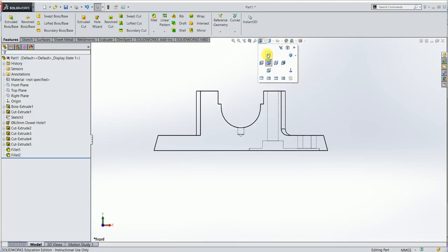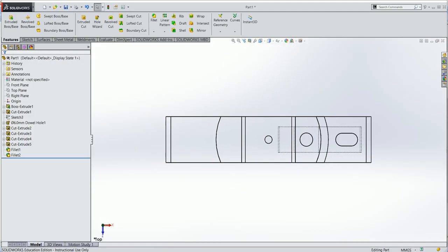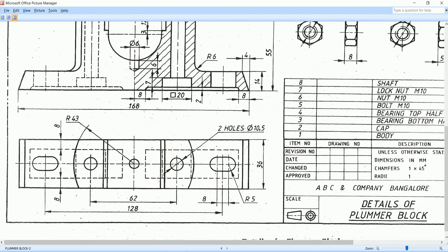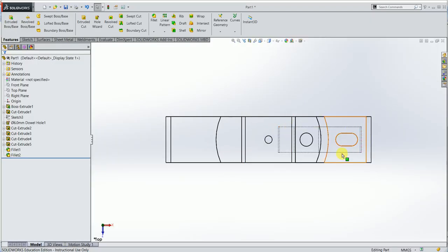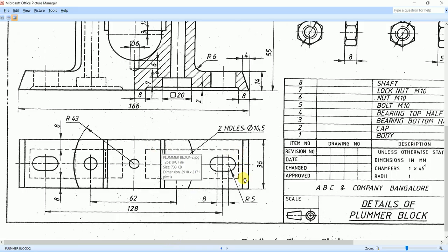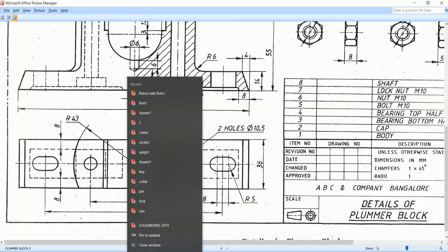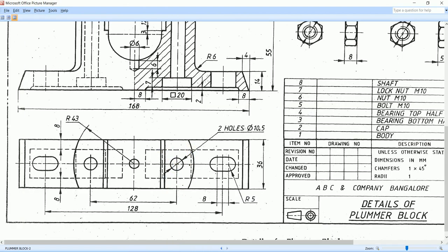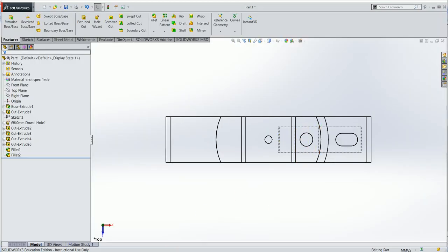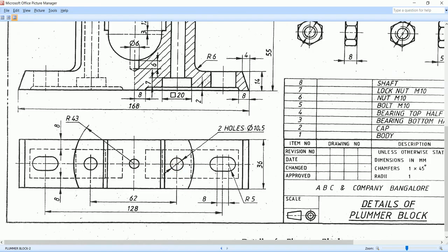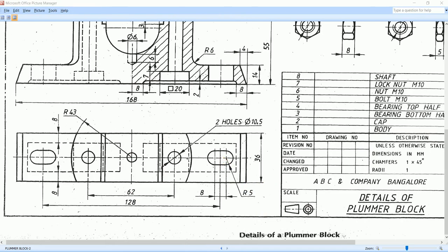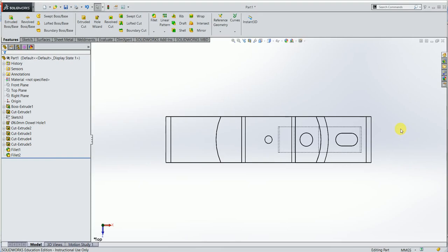And let's try to compare the top views. So now this is the top view. You can see this dashed rectangle here corresponds to this rectangle here, and somewhere here we need to have a square rectangle with dashed lines. That can also be seen here. And we have the circular wall here, which can be seen here, and we have the elliptical wall here. The same elliptical wall can be seen here. And we have two vertical edges here which correspond to these two.